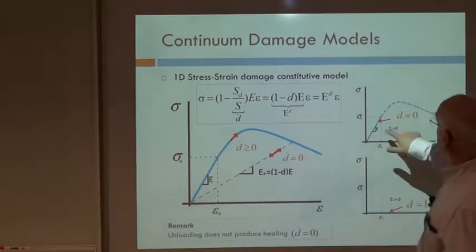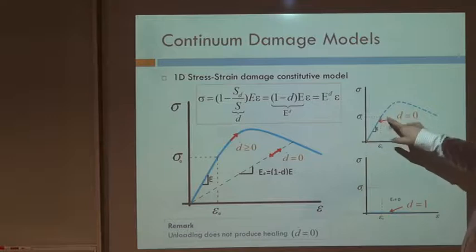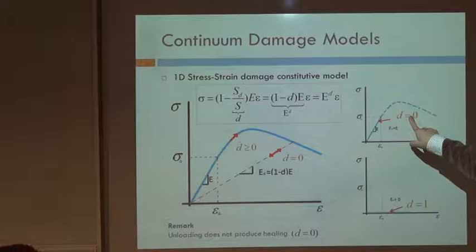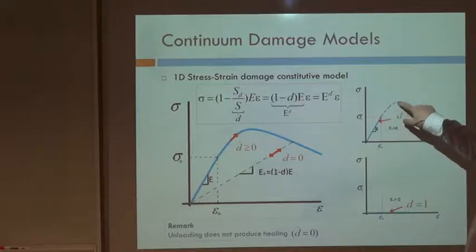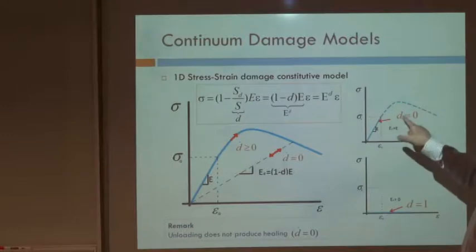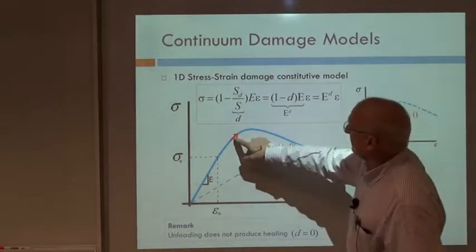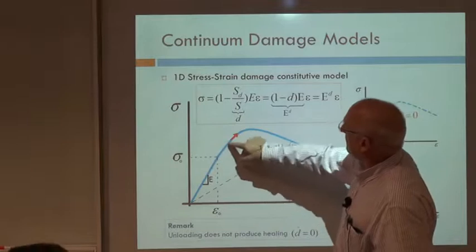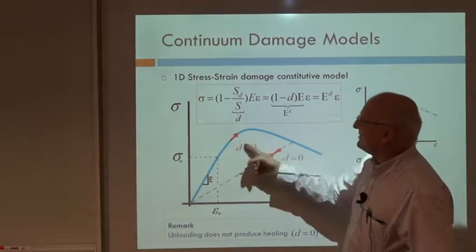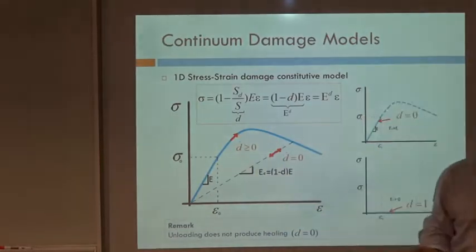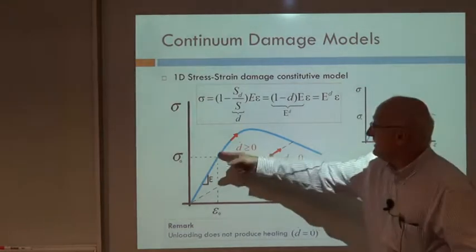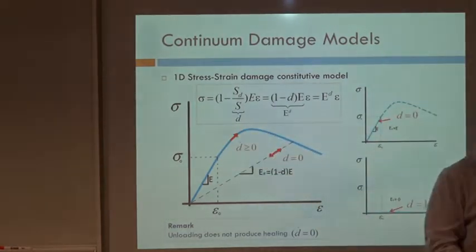Look that we can talk about the elastic branch, where the degradation is 0. The damage parameter, or damage variable, is 0. And beyond that, any nonlinearity, or the degradation of this d dot, the fact that beyond that point we have an increasing value of the evolution of the damage variable translates into nonlinearity of the behavior.